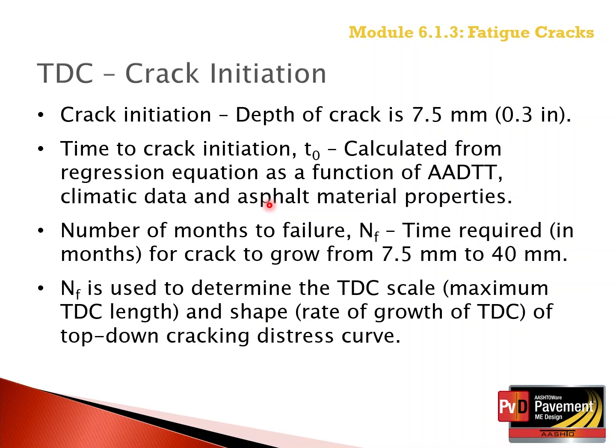So crack initiation is assumed to be at a crack depth of 0.3 inches, or 7.5 millimeters. So the program goes through a process to determine how much time, or the number of load applications, it takes to initiate the crack at the surface. The depth of that crack at the surface is assumed to be 0.3 inches.